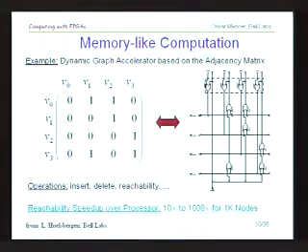Another newer architecture that shows a different data structure and a different algorithm is, let's say we want to have a graph and we want to solve the reachability problem on that graph. Usually you need to implement the graph as pointers, and you follow the pointers and you figure out if you can go through this entire graph to go from node 1 to the second node. And here is an array-like structure that takes the adjacency matrix that I have on the left, and you can see for each one in the adjacency matrix there is a corresponding OR gate in the architecture on the other side.